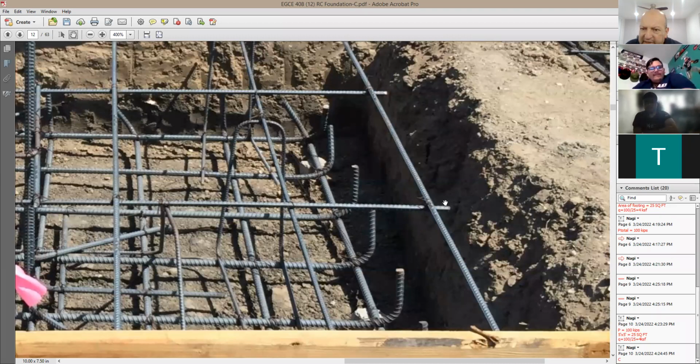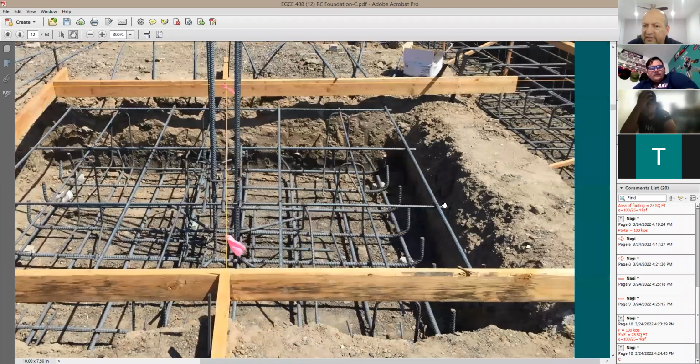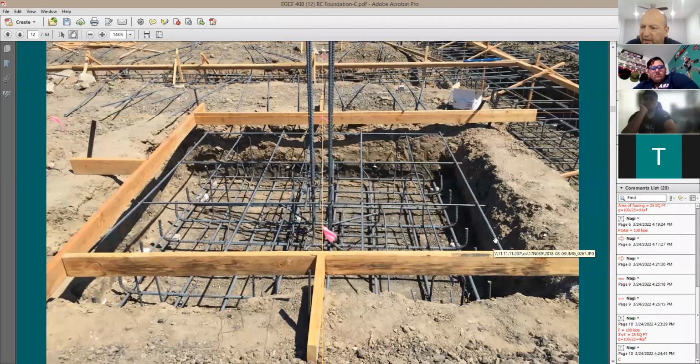They don't want me to come and say, this is not enough cover. So they give me more cover than I need. So actually this footing, if it's supposed to be 10 by 10, they build it like 10.5 by 10.5 feet. So I'm okay with that. I mean, they put a bit bigger footing. I'm okay with that. And look at the reinforcing. You have 9 bars here, 9 bars there. And they're supposed to put, let's say, for number 5, they just put, look, like 6 number 5. So I'm okay, yeah, put more reinforcing.